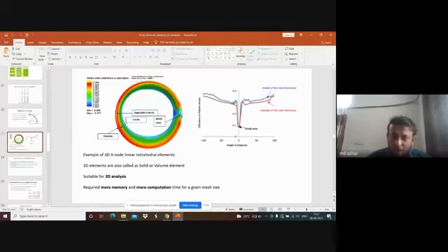Opposite to the weld, you can see the strains are very low, of course, because the weld is hard to deform, and towards the weld the strains are very high. You can even plot this, and you can see at 0 degree here the weld is high, and all these things.